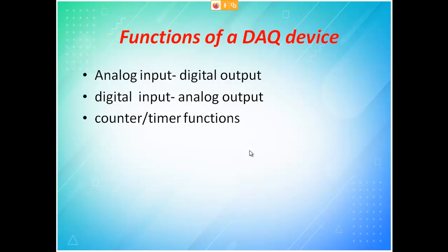Timer and counter are both the same; the only difference is that for everything you need a clock. Both counter and timer require a clock. If the clock is external, then it is a counter. If it is your own clock, then you call it a timer. So timer will run on inbuilt clock and counter will run on external clock. Only that is the difference.